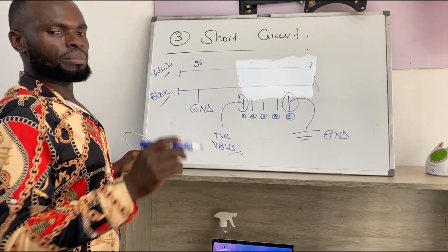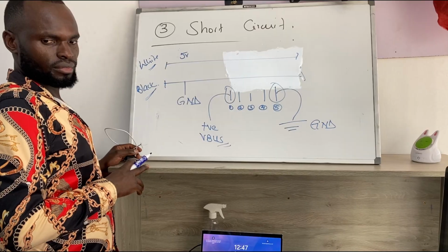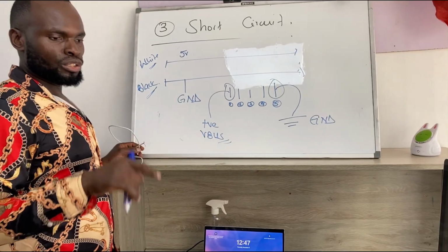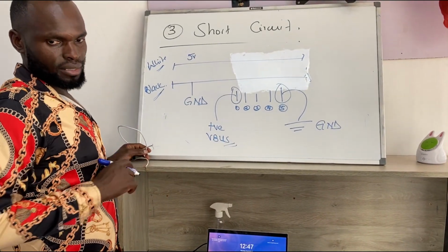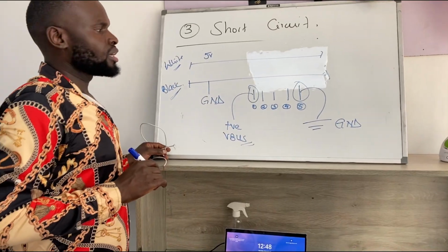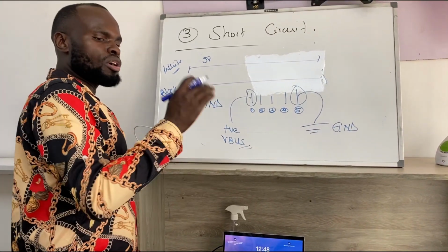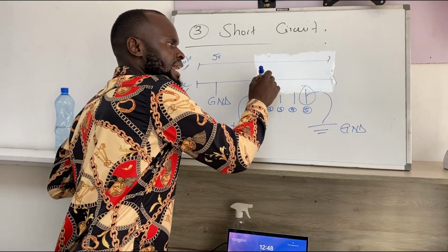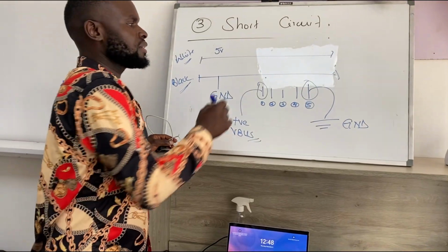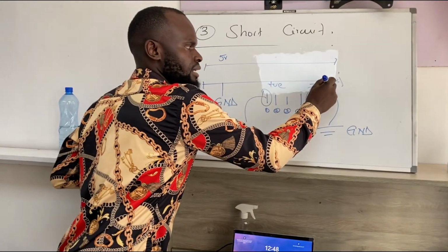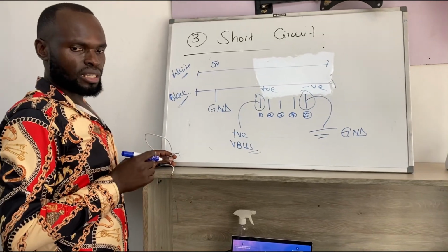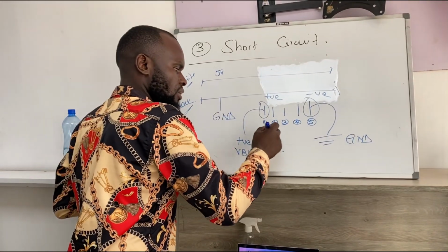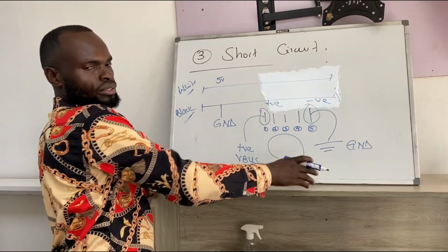So you might be replacing a charging port. If you are replacing a charging port, the charging port has pins. I'm going to show you after this. And with those pins, you will have to connect them or link them to the board, either the subboard or the motherboard. So with those pins comes the polarity of the motherboard. If this side is supposed to be positive, this side is supposed to be negative, the very far ends, the opposite ends of each other, so that if you put your charger, there will be a flow of current in that order. It is going this way to return to that side.